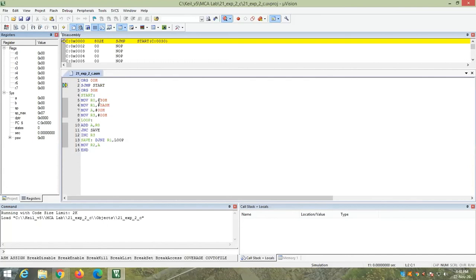Now we need to go into the for loop. In this we need to run the code such that first we clear the A register and then add the R0 register to it. Then if there is a carry, we increment the R3 register. Then we make sure that this loop runs R1 times so we can get the multiplication of 30H and A0H.